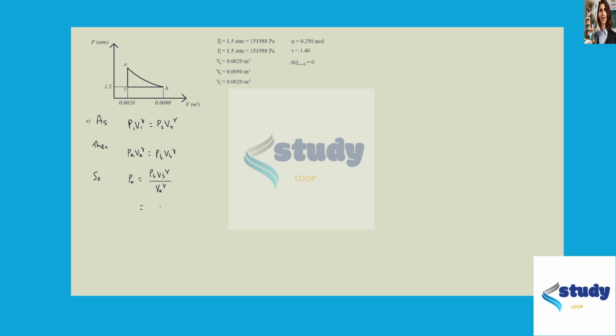By substitution of the numerical values we have, 1.5 atm times 0.009 meters cubed. This is to the power of the ratio 1.4. And that's all divided by 0.002 meters cubed, again to the power of 1.4.